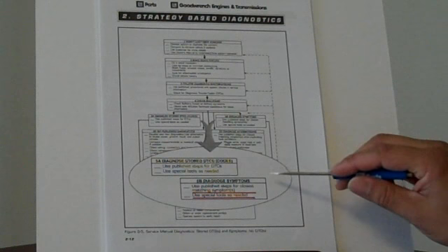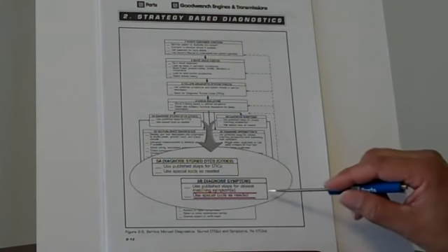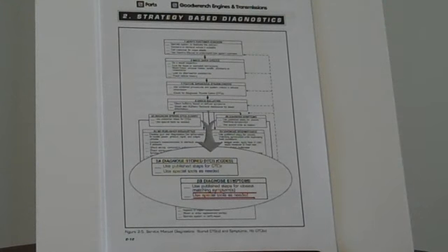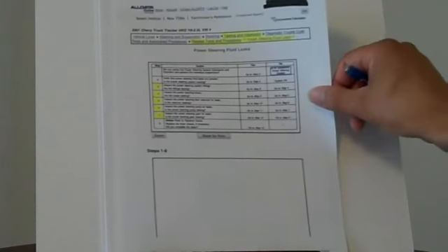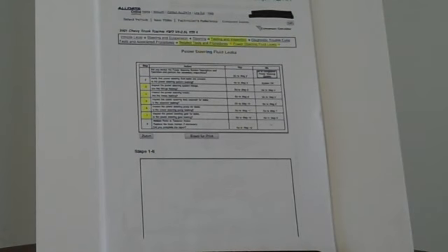Step 5. Diagnose symptoms. Use published steps for closest matching symptoms. Use special tools as needed. Now, following the symptom chart for power steering fluid leaks, it shows to inspect the more obvious components first, such as fittings, hoses, reservoir, pump, and then the gear or rack. The last step in this process is to operate the system to verify the repair.